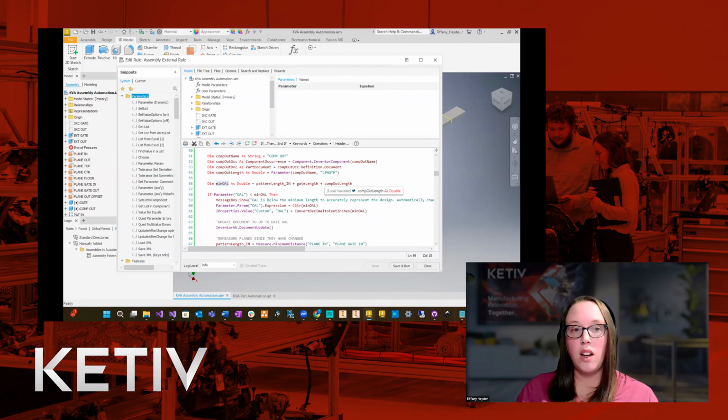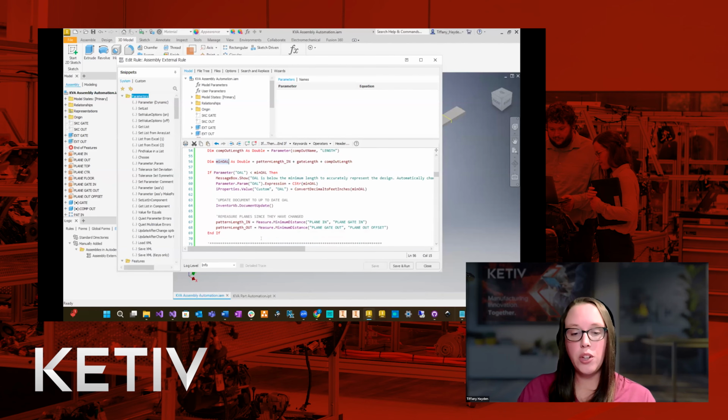So a lot of times in your code, you're having to error handle. In this case, we wouldn't want the user to input an overall length that's shorter than what we can do. So when you are putting in the code, you're saying, well, here's the minimum length that it can be. If it's anything other than that, we want to set it to something a little bit bigger and then drive the model. And of course, alert the user, but we don't want the model to error because we put in a bad value. We want to catch that if we can. So that's what this is doing.